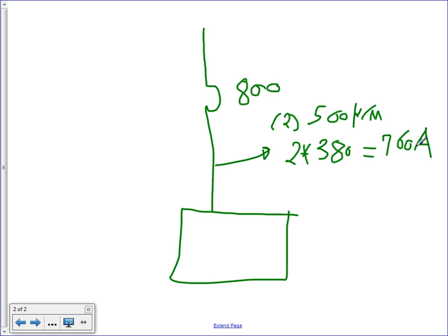So this applies for non-adjustable circuit breakers. With adjustable circuit breakers, you can go to the next step. If I can tweak the 800 down to 770, I have to tweak it down to 770. I can't keep it at 800. Any comments, guys? Any questions?